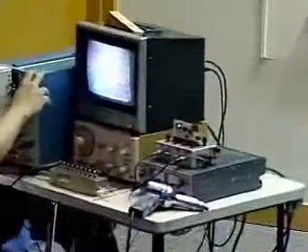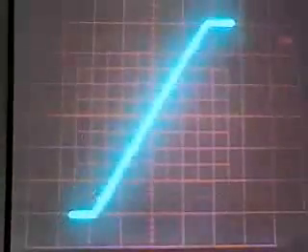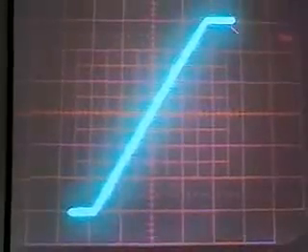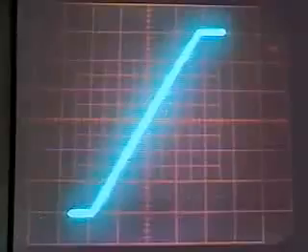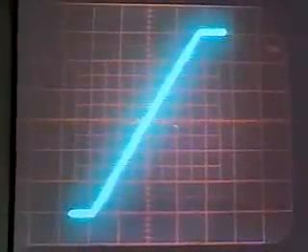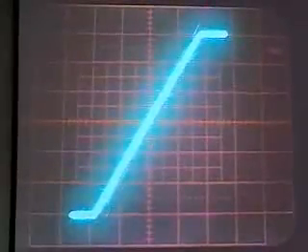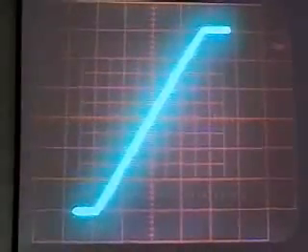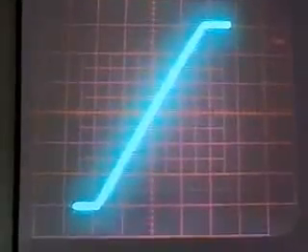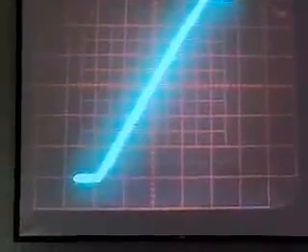So this time around, this is the transfer function, the V naught versus V in. Notice that this time I have similar scales on the X and Y axes, and this has a slope of 10. This is the point where the amplifier saturates at plus 12 volts, and this is minus 12 volts. This point here is 0. So this is V in, V out, plus 12, minus 12, and this slope is 10. What I'm going to do now is hit the op amp to the wazoo, and this ain't going to change, because it's my external resistors that control it, independent of the value of A, provided A continues to be very large.